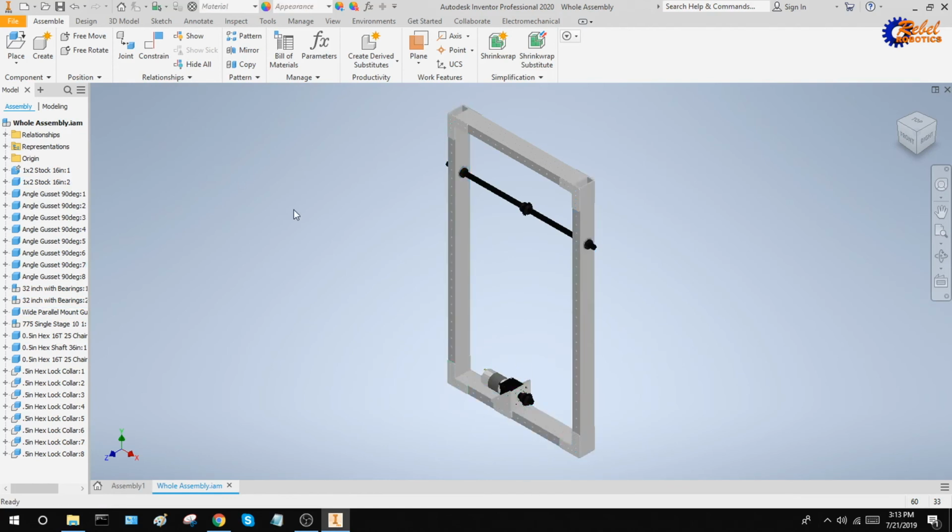So to summarize, always when you click the home button, have your assembly oriented so that homing your view gives an appropriate view of the entire assembly. Second, if the orientation is off, constrain your assembly to the appropriate planes, make as many constraints as necessary, and then finally delete those constraints and then ground one part of the assembly. And if the assembly is constrained correctly, nothing should fall apart.